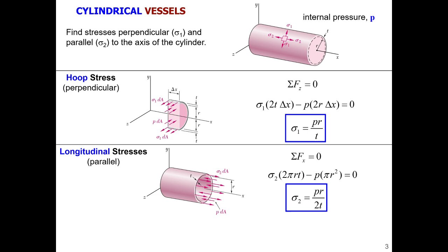Well, okay, it's normal. Some materials will fail when we exceed the maximum level for normal stress, right? But some materials are more sensitive to shearing stress and will fail first when the maximum value of that is exceeded. So that's why we're interested in this situation. Maybe if we use that type of material, the shearing stress will exceed the maximum level. Okay, so we know this sigma 1 and sigma 2, and in fact, an important point here is that these are what are called principal stresses.